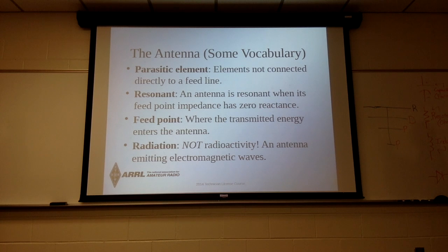Preferably, you want your antenna to be resonant. And we talked about resonant a few, like 20 minutes ago or something. Resonant means there's no reactance, there's only resistance. So there's zero reactance, and that's good if your antenna has zero reactance. That means it's like the maximum effectiveness, maximum efficiency.